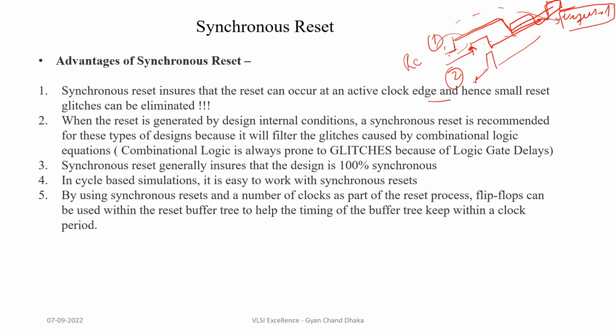But if our reset pulse is something like this, which is not a real reset pulse but a kind of glitch, a small glitch in our reset pulse, then with the synchronous reset technique this pulse can be eliminated, because the width of the pulse is very small, and it won't be detected by the design. So our design will correctly not reset. This is an advantage of synchronous reset.